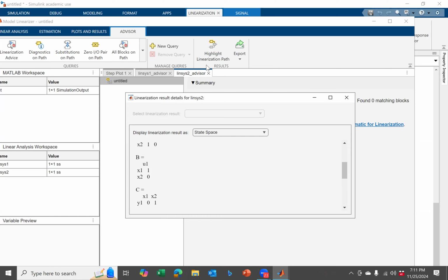So what you need to do is identify the inputs in that Euler-Lagrange function. Where are you controlling? Then identify the inputs, identify the outputs, and perform the linearization using MATLAB. And once you do the linearization, you can use your PID control to control the plant. Everyone understood this? Yeah.